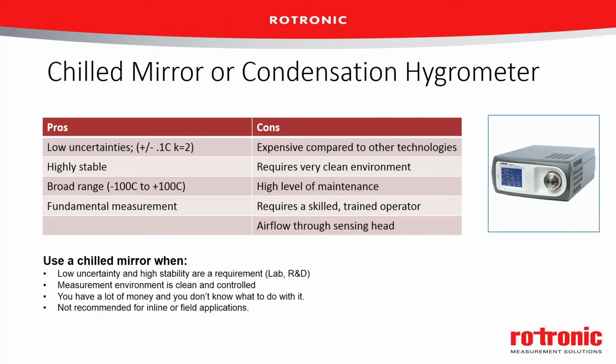They are highly stable. Since we're talking about temperature sensors being our measurement technology, those can be made to be very stable over long term. I've had chilled mirrors going for calibration annually over the period of about 10 years and never actually had the values adjusted. Some of them can be that stable.